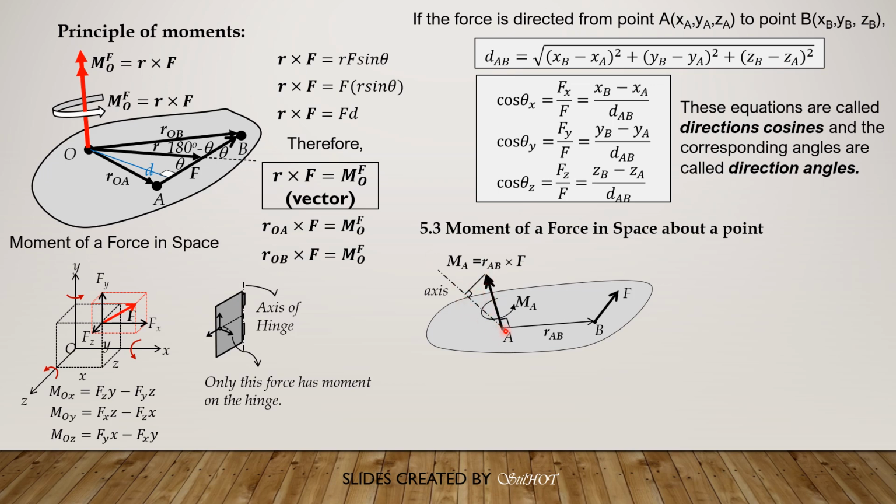Because we have formed a right triangle, and if the angle between this moment vector and the axis vector is beta, then that component is simply MA times cosine of beta. So in other words, moment about the axis, which is a scalar, is equal to MA times cosine theta, the component of MA. That's the moment of the force about an axis, and it is a scalar.